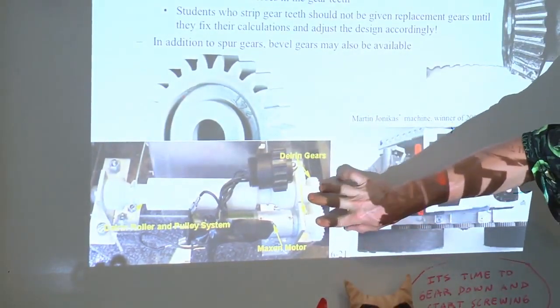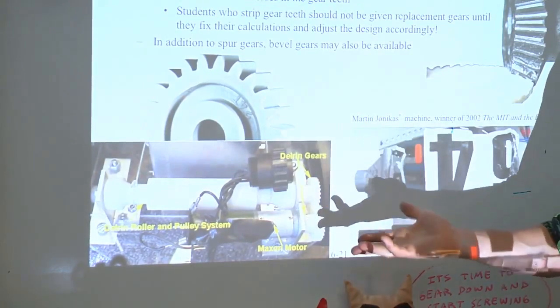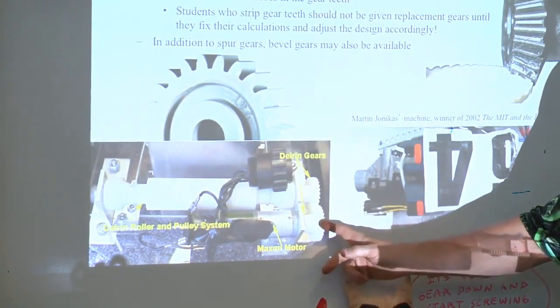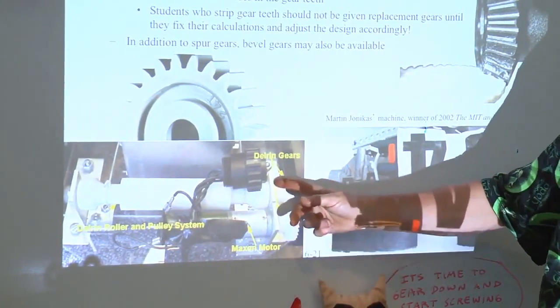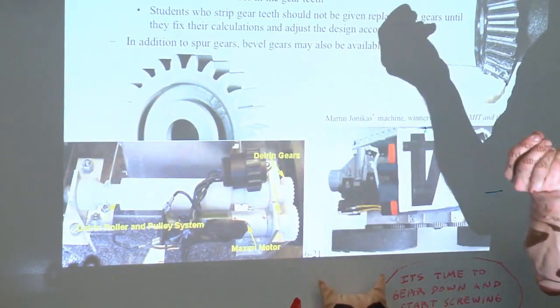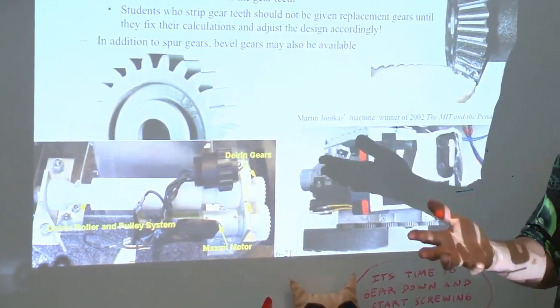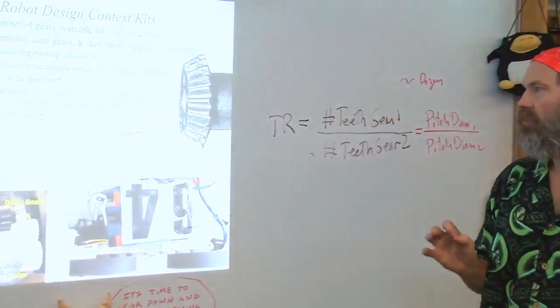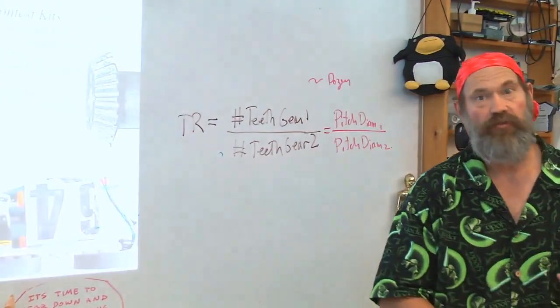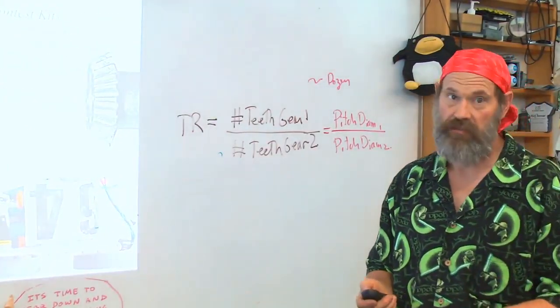Just took these two gears, flipped them around, problem went away. Putting where the forces occur back close to this structure that resisted the force, I tightened the structural loop up, got rid of the deflection problem. Okay? Very, very important to be worried about how you mount the gears. We'll show you some more examples of that.